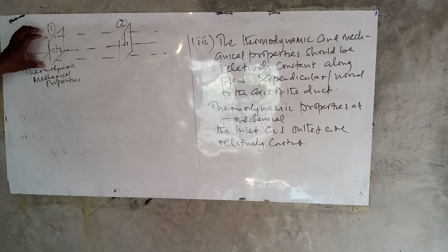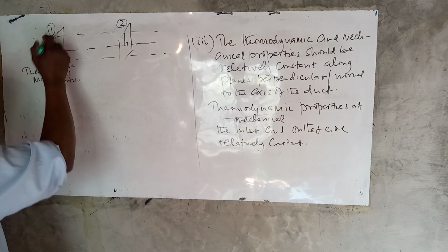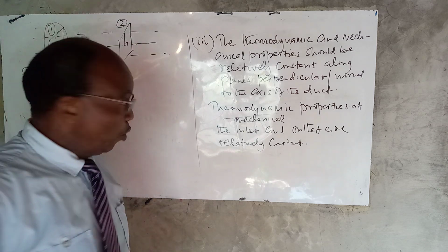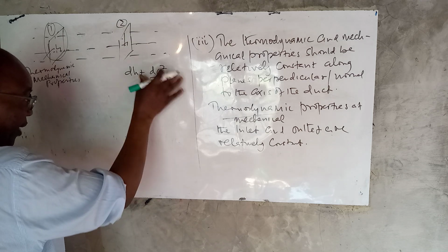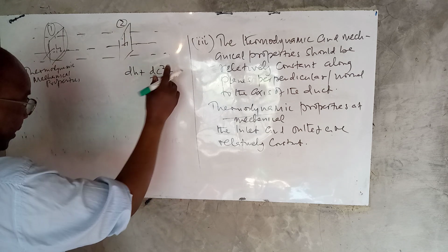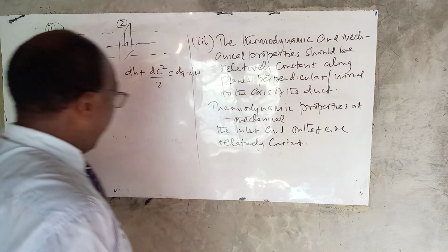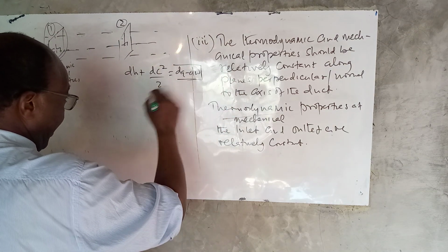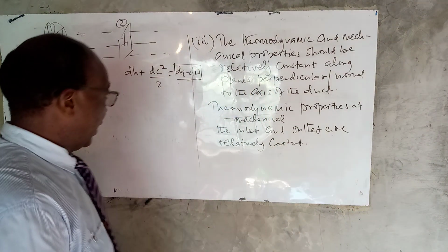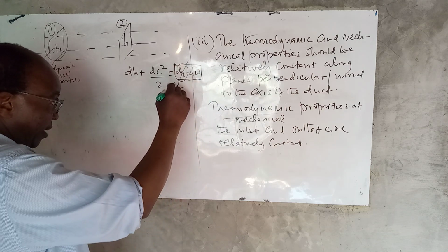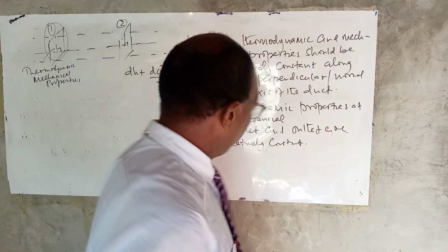For this flow to be a case of a one-dimensional steady flow that is perpendicular to the duct, that means if you have properties here, remember, we have our steady flow equation, the change in enthalpy plus the changes involving kinetic energy. We have that this is dq minus dw. So if you are dealing with a situation where we don't have any work or heat involved in this transfer, because if it's isentropic, then friction is negligible, or dq is thought of as zero, and obviously we are assuming that there will be no work.